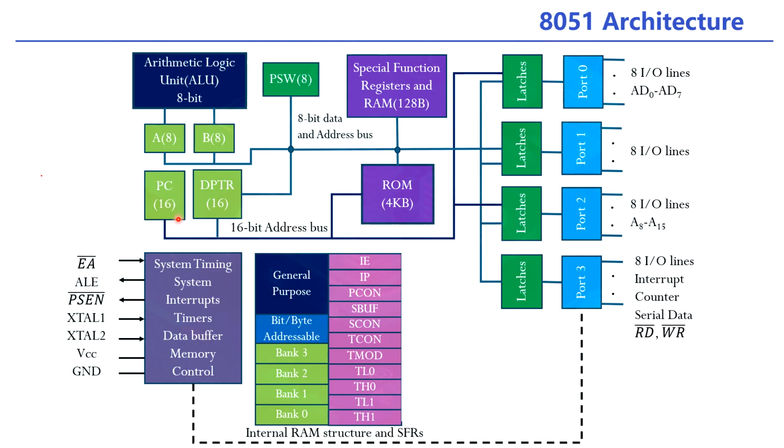One of the most important things to observe is that in the 8051 microcontroller every register has its own address, but the PC does not have any address. Why? Because it is always pointing to the address of the next instruction, to execute your program sequentially. This is the function of the PC, and one more important thing is that it does not have any address.